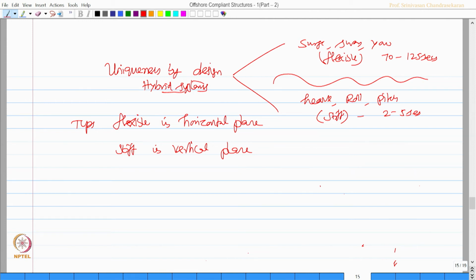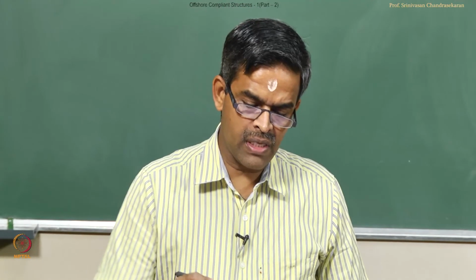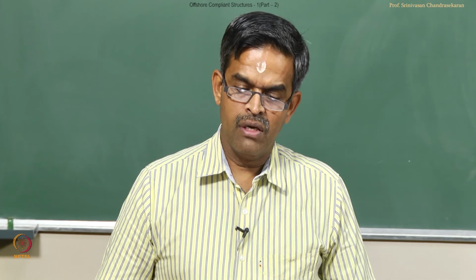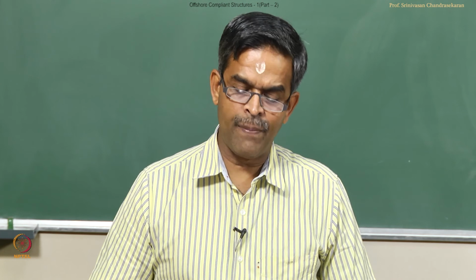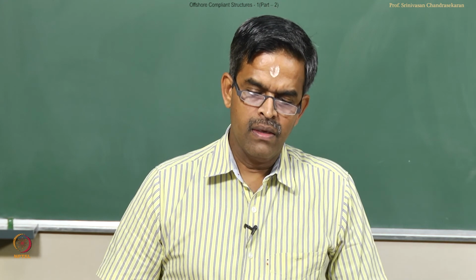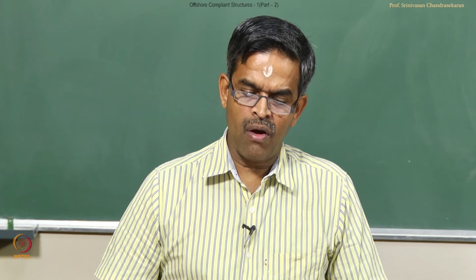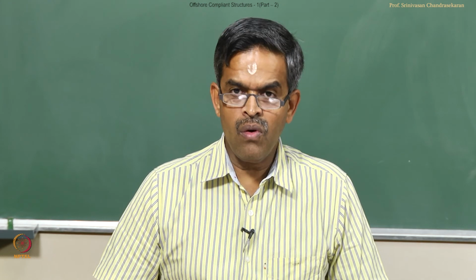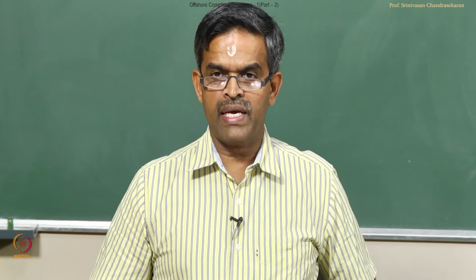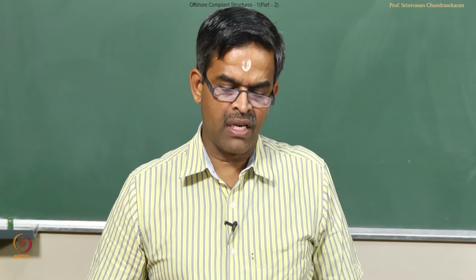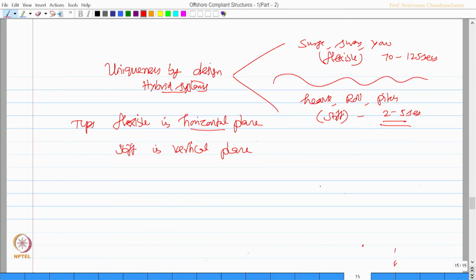because surge, sway or displacements along x and y, which is horizontal plane, and yaw is rotation about z axis, which will also happen on the horizontal plane. Similarly, heave is displacement along vertical plane, that is z axis, and roll and pitch are rotations about x and y axis, which will also happen about the vertical plane. So, for low periods they are stiff, therefore it is stiff in vertical plane. For larger periods they are flexible, therefore they are flexible in horizontal plane, and put together this is called a hybrid design concept in offshore platforms.